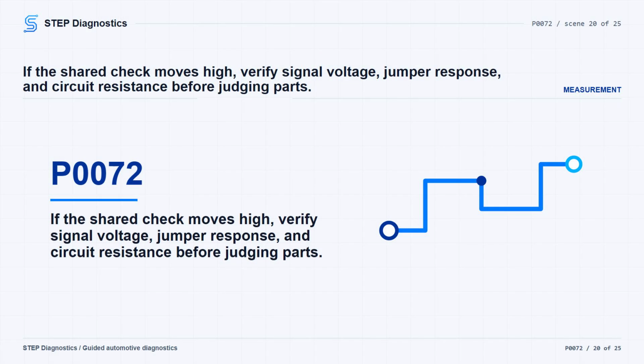If testing moves you into the typical circuit high side of the shared circuit check, disconnect the temperature sensor harness connector and measure the temperature sensor signal circuit voltage with the ignition on. The signal circuit voltage should be between 4.9 and 5.6 volts. With an active fault, monitor the scan tool and connect a jumper across the terminals with the ignition on.